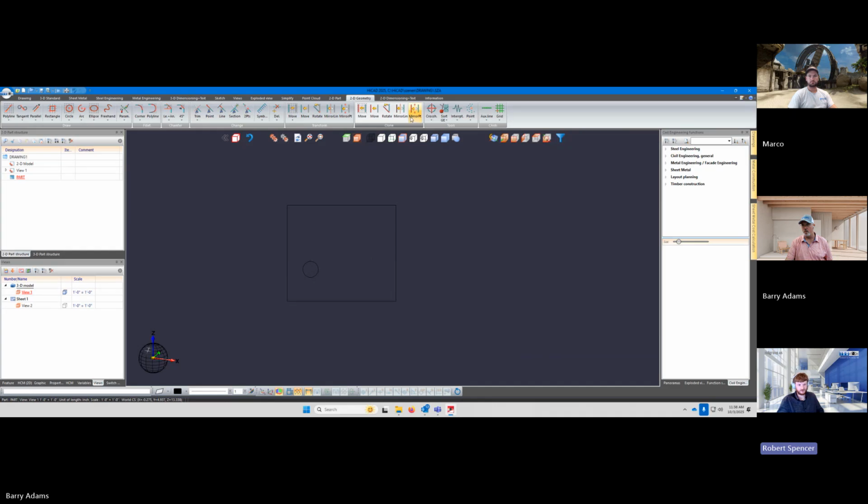Let's just use that first clone button. What does that first one say? Copy plus move. What's the one to the right of it say? Copy plus move. Okay, so the first one gives you a snapping grid. The second one is just standard. You've got to key in the values. Now you can still use that first one and key in the values. So it's a little bit redundant, but it's a slightly different way to do the same thing. I would just suggest trying it, but let's try the first one this time.